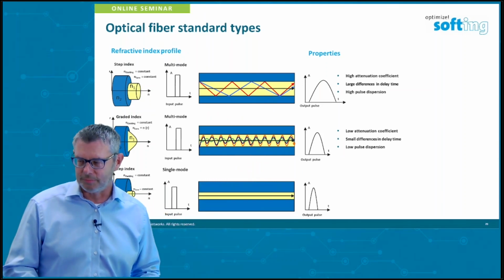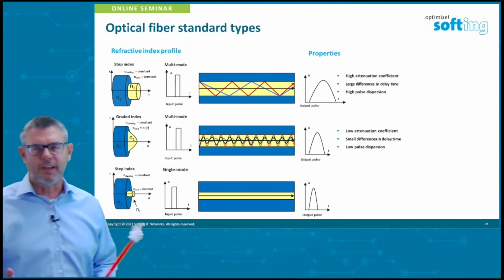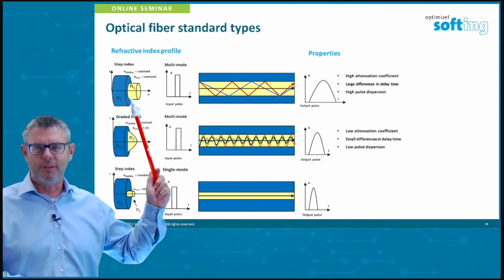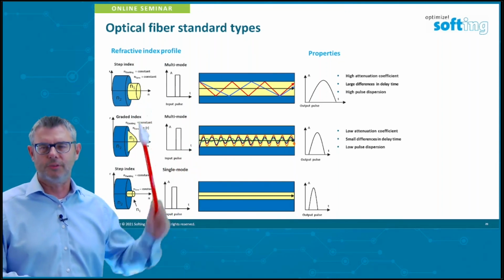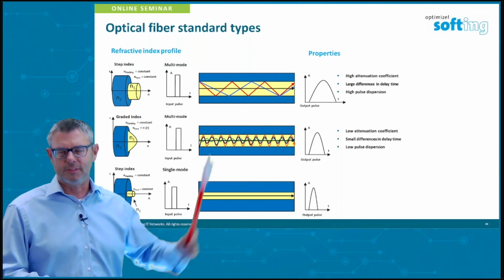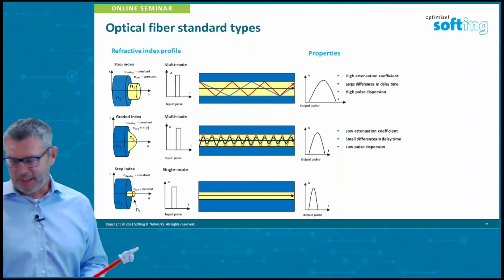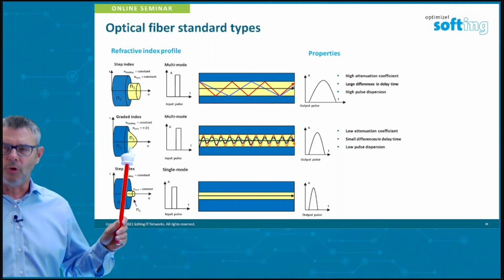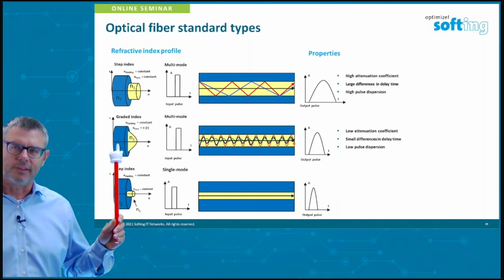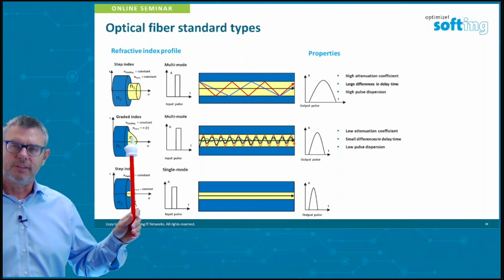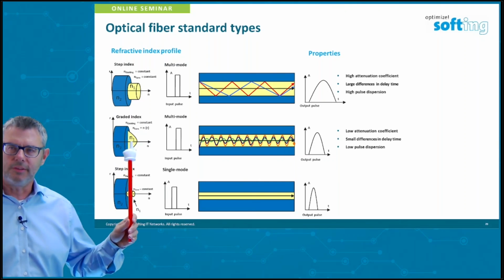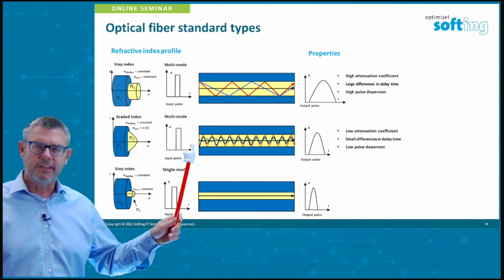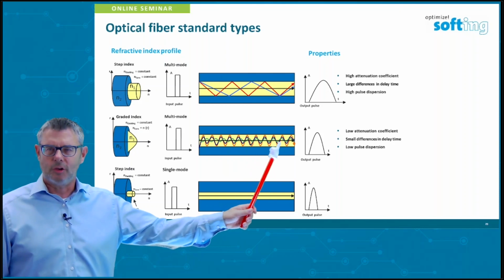That's the basic principle. Okay, and there are three kinds of fiber optics nowadays. This one is more disappearing: a step index, where you have only two different indexes of refraction, and this gives you this behavior of how to transmit data. Nowadays, we are talking about graded index fibers and multimode. So there is not one index for the cladding and one index for the core; there are dozens of indexes in this core.